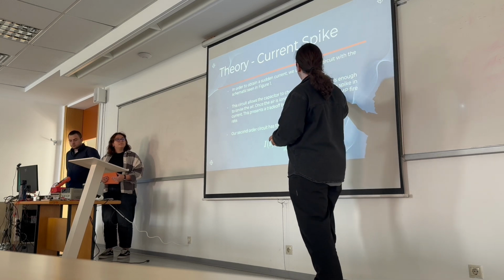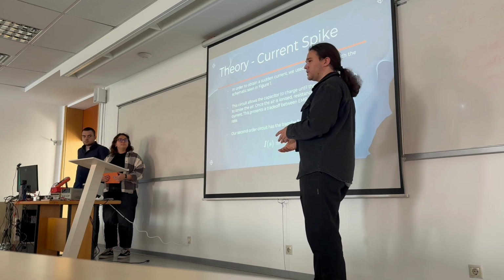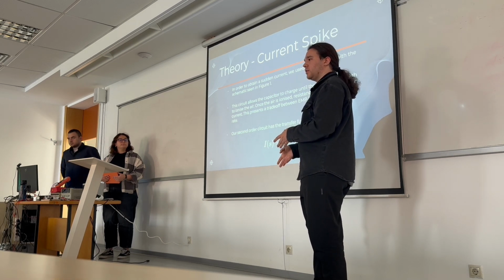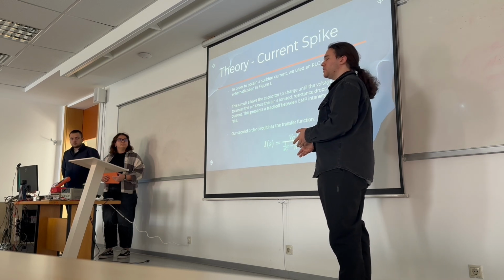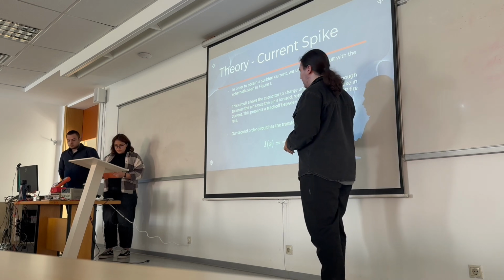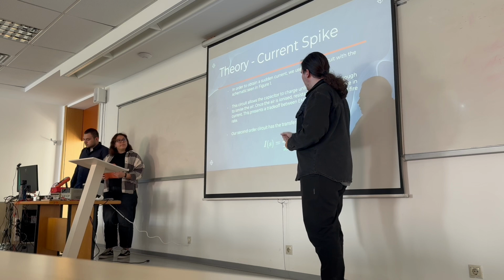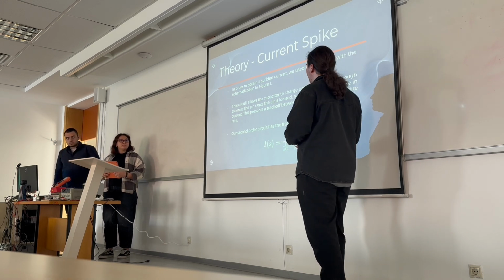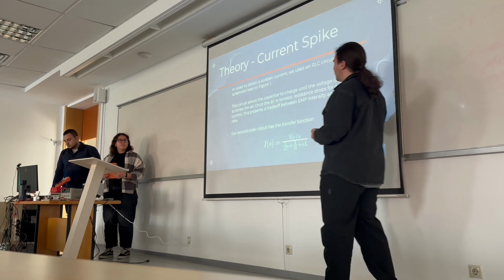We will charge the capacitor until a certain voltage, until it is enough to ionize the air in the spark gap. Once the air is ionized, its resistance drops significantly, and this allows for the discharge of the capacitor. Therefore, as you can see, this is the current transfer function. The higher the voltage of the capacitor, the higher the current. However, the higher the voltage, the longer it takes for our capacitor to reach that voltage. So we have a trade-off between EMP intensity and EMP firing rate.